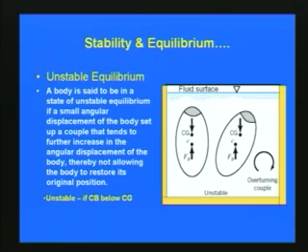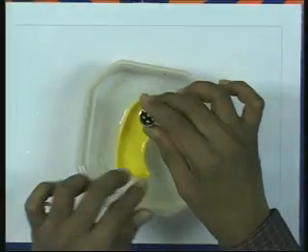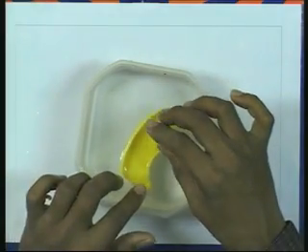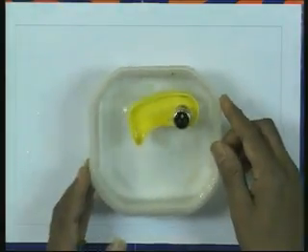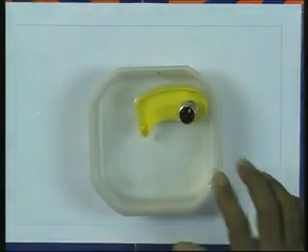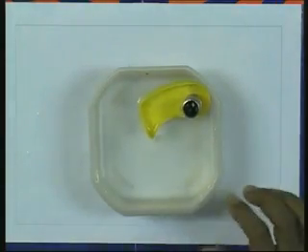I am just putting a small weight upon this floating body, and then what happens is, if I am giving an overturning moment to this body here, so as we have seen, it is said to be stable equilibrium if it is returning back to its original position, but here, when it is overturning, an overturning couple is formed and then it is going down.